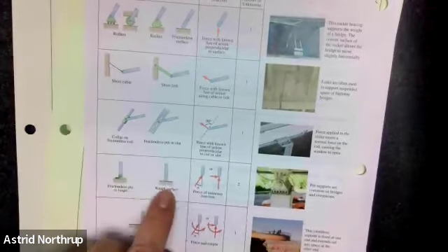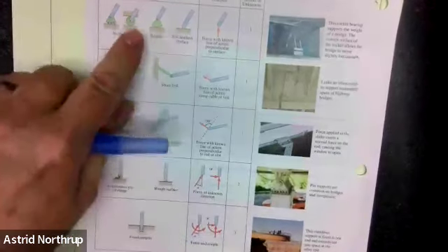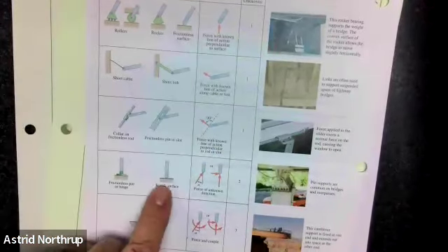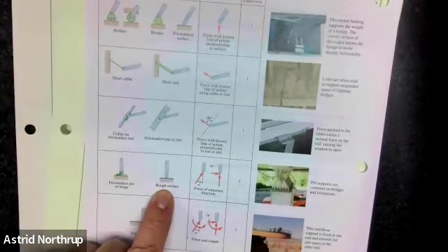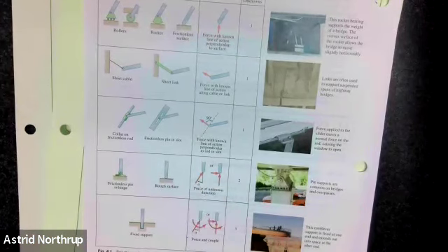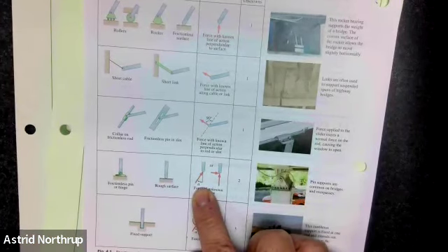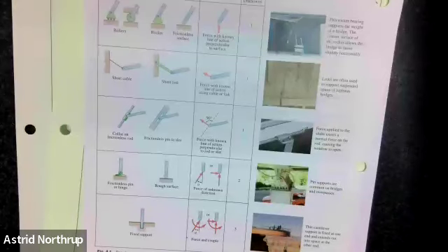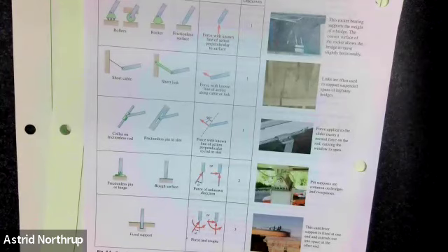Now, if you have a bar like this that is not sitting on a frictionless surface, but rather is sitting on a rough surface, it can bear a force in either direction. Now, the actual force is going to have a direction something like this, but it's a lot easier executionally to draw the force as having an x component and a y component and possibly a z component. All right, so if you draw it at an angle, you're going to have to resolve it, so you might as well just start by calling it out in coordinate directions.